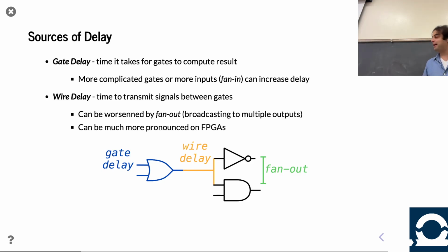So with FPGAs, if you spend time optimizing for them, you'll find that you want to have limited fan in, limited fan out, limited wire delay. You really have to get a very optimized design to really minimize your delay, versus on an ASIC, where sometimes you can just do a decent job, and modern transistors are very, very fast. As long as your design is not poorly made, you can get a decent delay if you don't have a very aggressive clock period.